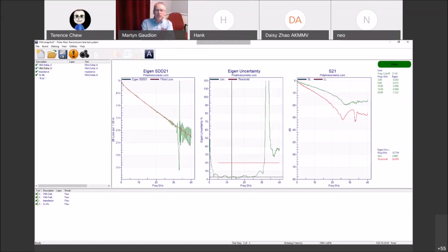Okay, so briefly in summary, we presented the mechanisms behind impedance and insertion loss, how the key factors that influence impedance are quite different from those that influence insertion loss, how you can model insertion loss, and then how you can microsection to look at the physical parameters you need to put into the field solver, and then looking at the measurement, how to understand that all you can see from measurement is total loss.